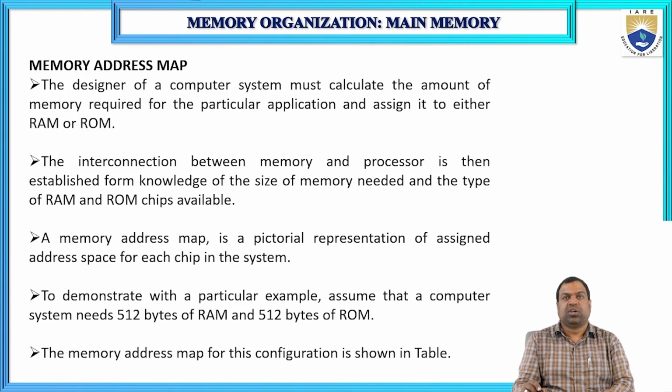Memory address map. The designer of a computer system must calculate the amount of memory required for the particular application and assign it to either RAM or ROM. The interconnection between memory and processor is then established from knowledge of the size of memory needed. A memory address map is a pictorial representation of the assigned address space for each chip in the system.